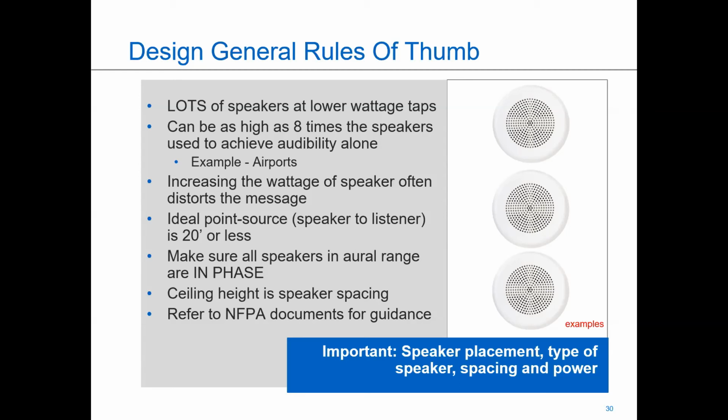And the way to do it is by design. Somebody is going to use modeling software with the speakers that you're using, and they're going to lay them out. That's the first thing that has to be done before you run all your circuits and figure out how many amps you need, the power supplies, and what you're doing. Somebody's going to run these models, and then it's going to be tested. And that's the part in the field where the taps may change. The speakers need to be in phase. The ceiling height has to be discussed. It's all part of it.